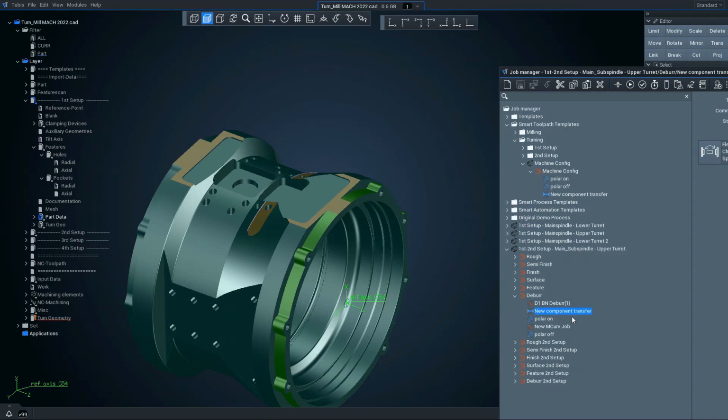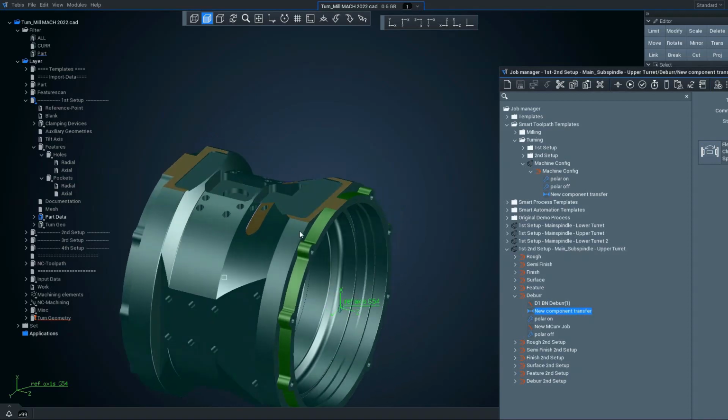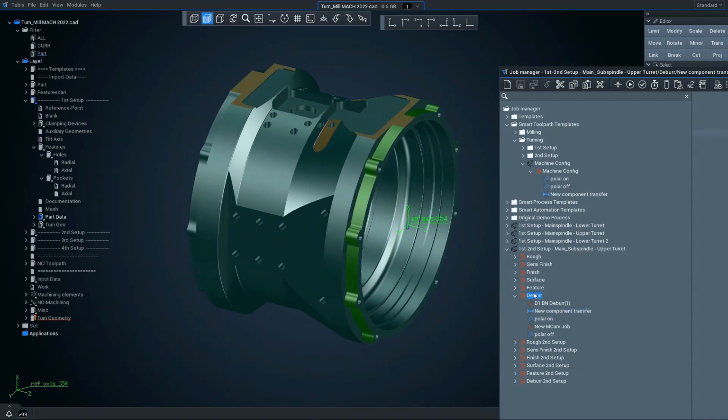Now the component transfer will automatically tally the dimensions from your first reference point in relation to the job to the reference point for the back half of the job, and create an automatic component transfer. This is an all-in-one operation where we just add the component in, and Tebis automatically takes care of the transfer of the component through the virtual machine and through the stated chucks. So in this instance, if we just have a quick look at this in the virtual machine,